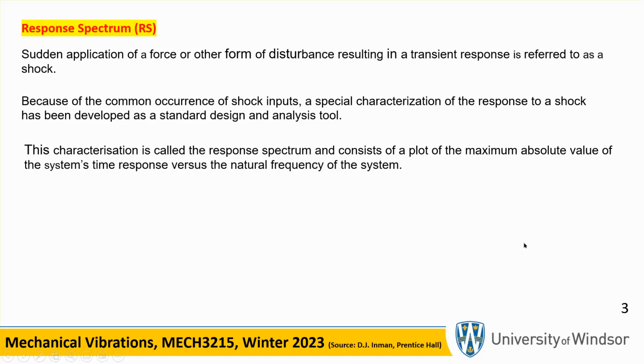Our author Inman refers to it as response spectrum. Now, a particular methodology has been designed in order to do problems like that, and it involves getting the maximum deflection of the block, or the thing that you want to investigate, over the entire duration of the vibration.